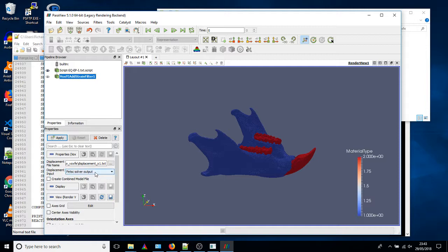This is from this sort of version 0, albeit slightly converted, but it's from a solver that we call ParaView. So you have to change that to that option. Click apply again. Again, it takes a little while to read through all that displacement data and recompute the strains. So again, should be there in a moment.